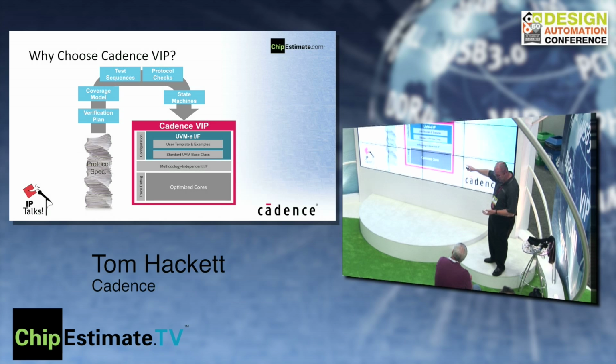This gray box in the middle, this methodology independent interface, is for the many people out there that are still using just regular plain vanilla Verilog or VHDL to do their test benches. Some people use C or C++ for their test benches. So they can connect to their test bench through this methodology independent interface. And then that connects to the optimized core. And there's cores for simulation and also for acceleration.